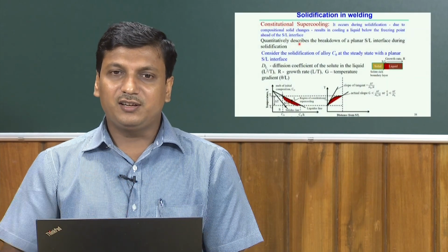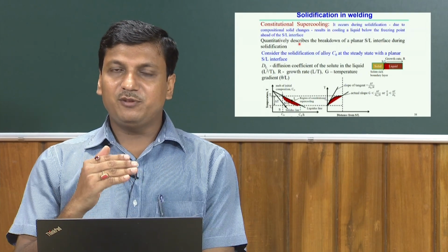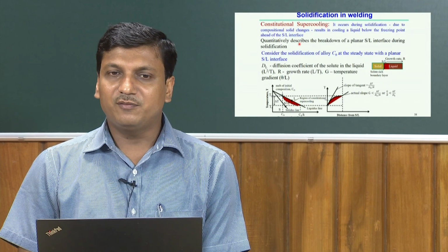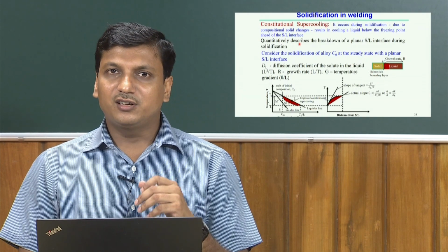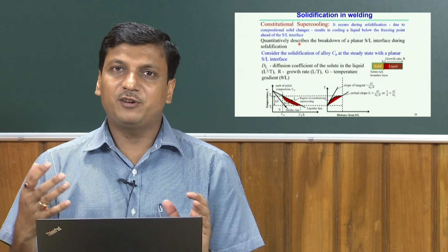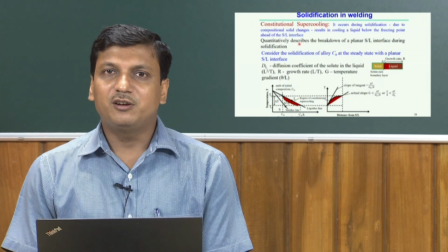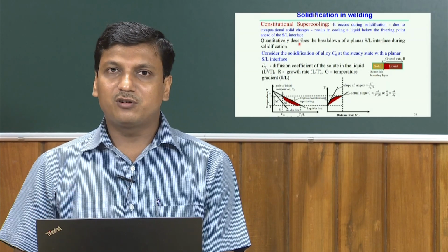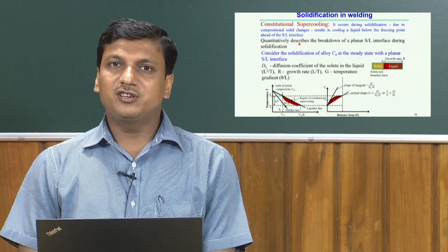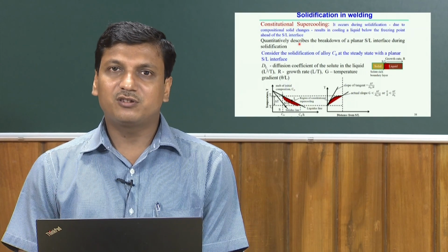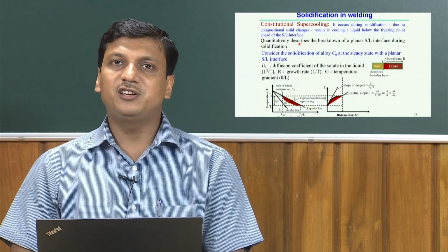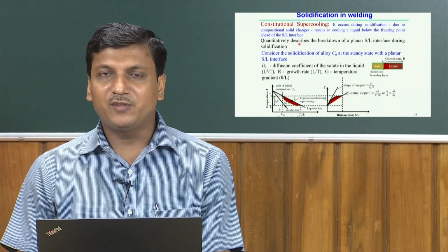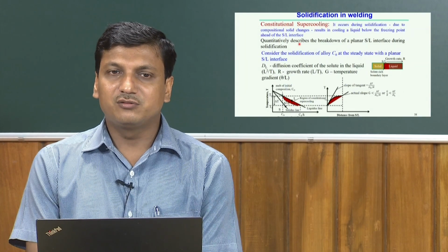So, in the case of pure metal, it can be well defined from the time versus temperature diagram, and this amount of supercooling depends on, or the values are different for, different types of material. Normally the amount of supercooling mainly promotes homogeneous nucleation, which in the solidification process is driven by the amount of supercooling, and is entirely different from the heterogeneous nucleation mechanism.